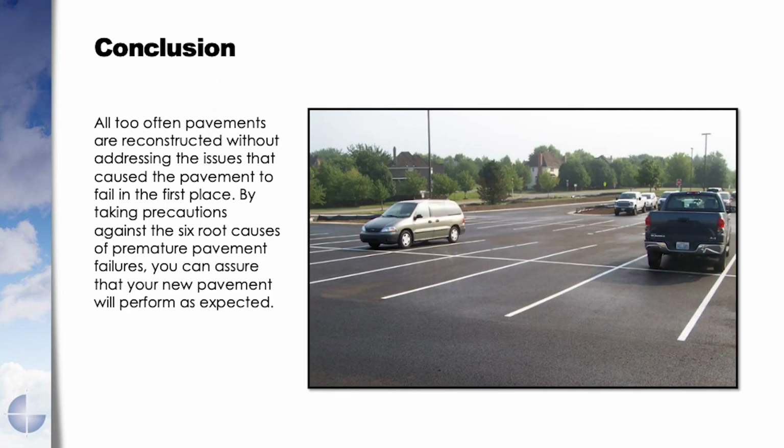So in conclusion, when you see a failure of your pavement, try to determine what's causing that failure. Look not only at the pavement, but around the outsides of the pavement. Look for those clues for subsurface water, clues of rutting or faulting concrete, and make sure that before you do a repair or full reconstruction that you address in your design phase these root causes of pavement failures.